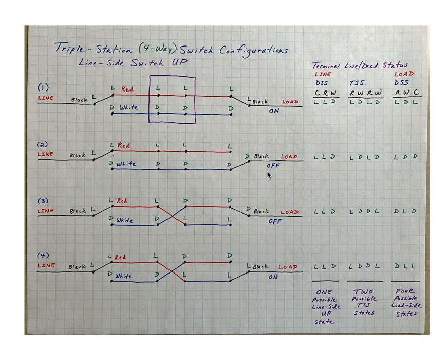Here you have off. You can see clearly that your live side's here, but it's not connected. There's no connection, so your load is not energized. And here's another way to switch it. Here you have your live side. It comes in. All right. Now your 4-way switch is switched. So this current goes this way, goes on to this traveler here, this traveler conductor, and nothing happens because you see the connection is broken. Anyway, you can study this on your own.